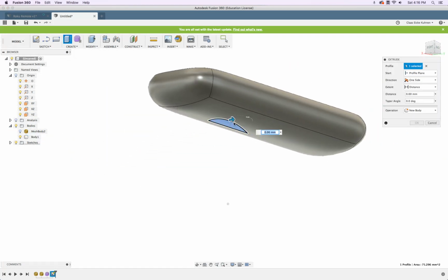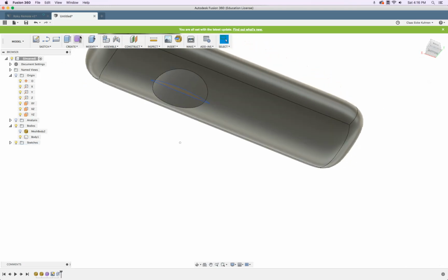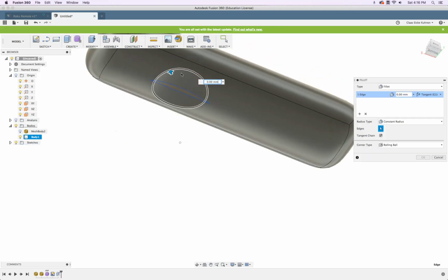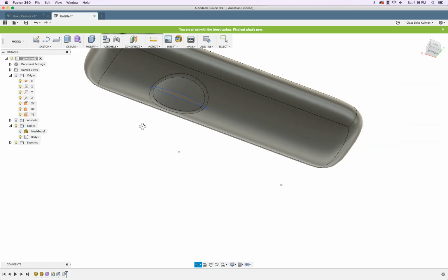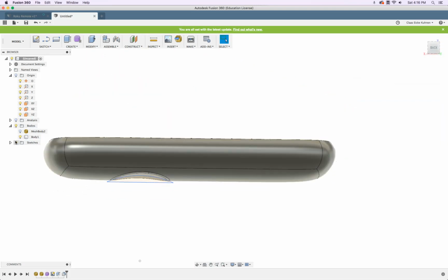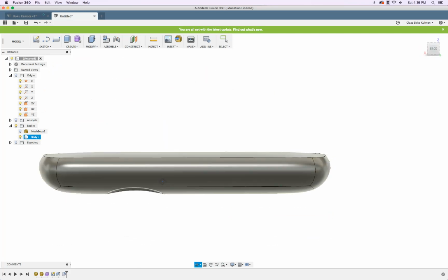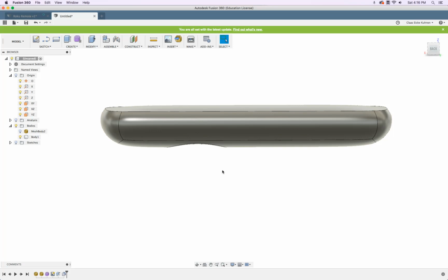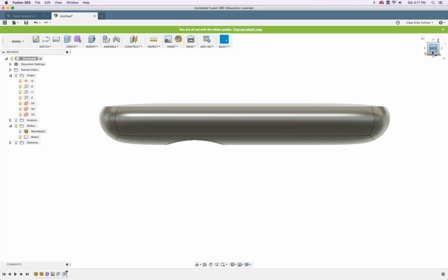Then I'm in model mode. I select extrude, cut both sides. Okay. And then fillet this part, maybe 2 millimeters, no, 5 millimeters. Yeah, this is good. Okay. There. So you see we can combine both tools, the way how a character modeler at Disney works and the way how an industrial designer works in Fusion. It just gives you perfect mobility between these two approaches in one program.